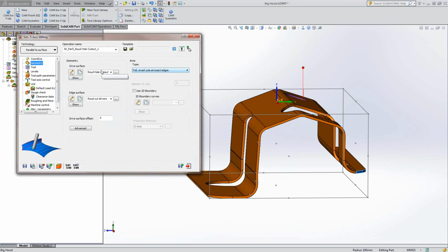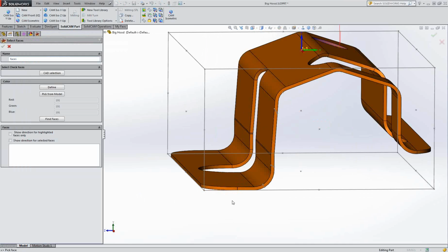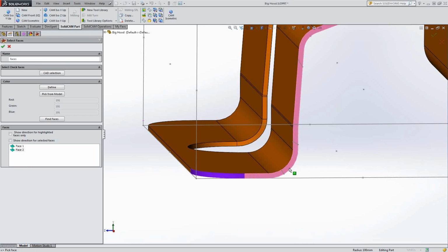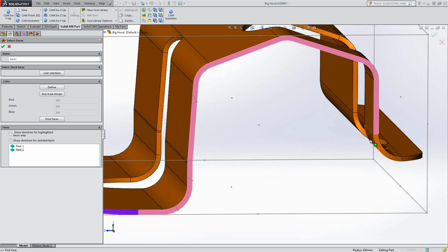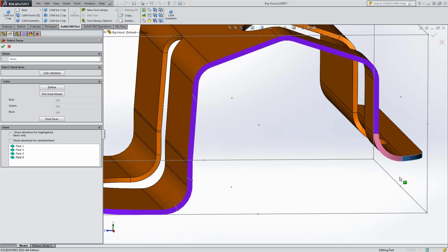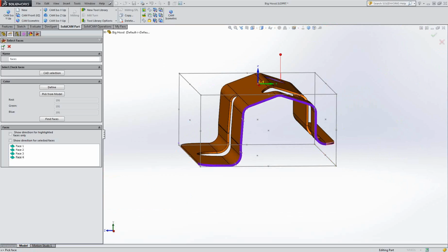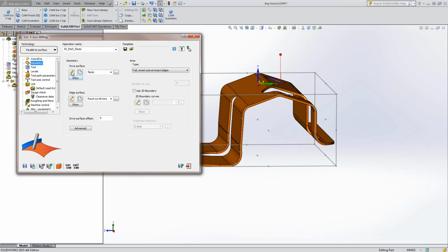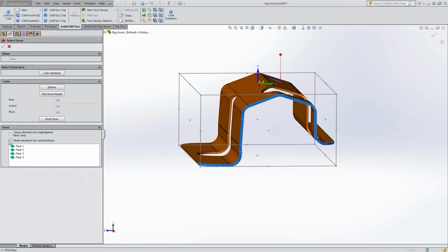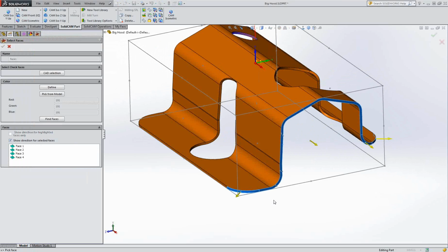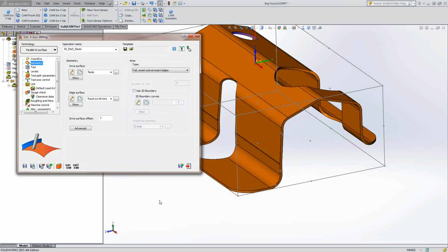And in here in the geometry, I'm going to choose my new drive surfaces, which are going to be these ones. That and that. Okay, let's go back and edit that and check to see which way the surfaces are going. I've created this from a surface with a thickening on it, so everything is working tickety-boo. However, if you get an IGES file that's come in from another program, and it's only a surface, you can have them going in many different directions.